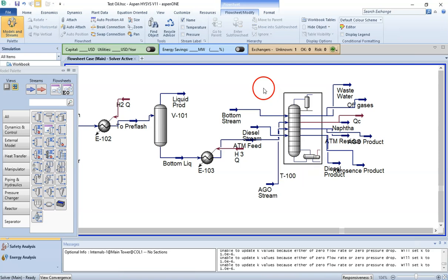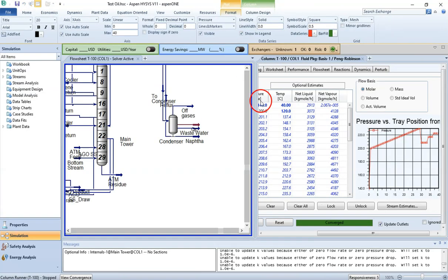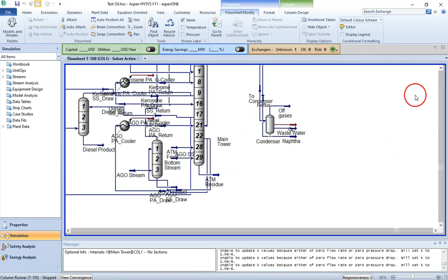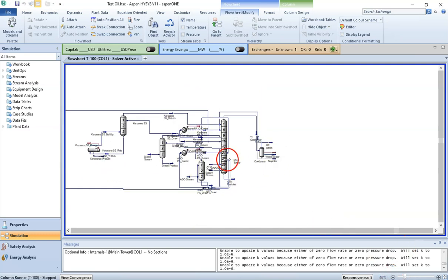I'm going to unselect this and show you. This will never be highlighted if it is not selected, so you need to select the distillation column. I will select it and you can see that it has provided more details, and you can enter into your environment here. Let's close this, and now these are those side streams that we were developing in our distillation column.